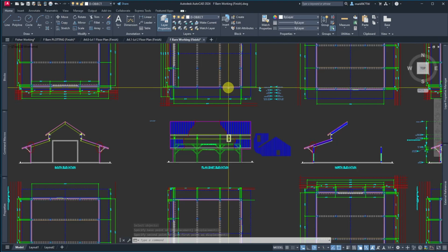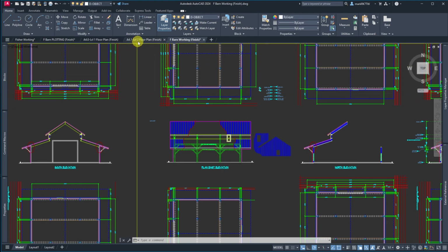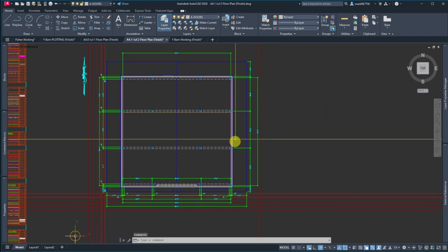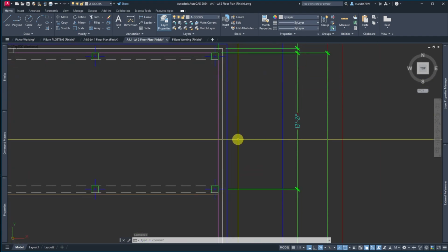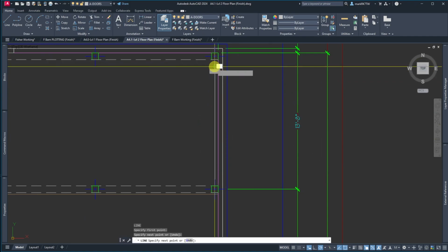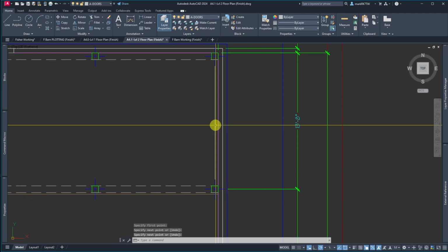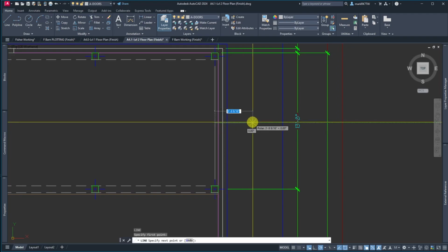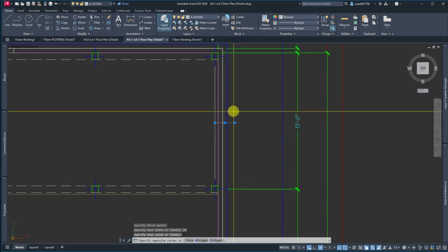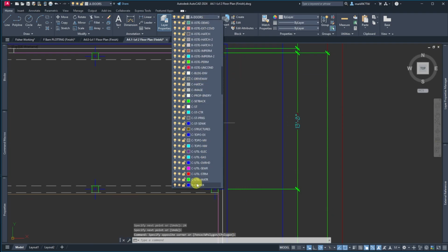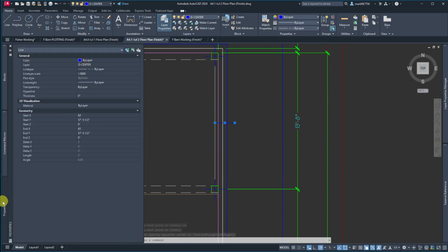Then in our floor plan view, if we're looking at the door, then on our right-hand side, on level 2, we should draw some windows here, just to show you how this works, and then I'll come in and finish it. So let's draw a line from here to here to find our center, and then let's draw a line from here. I'm going to pull it out 24 inches, and then I'm going to turn it to the D center layer, and then to make this look like a center line, this needs to be 12.